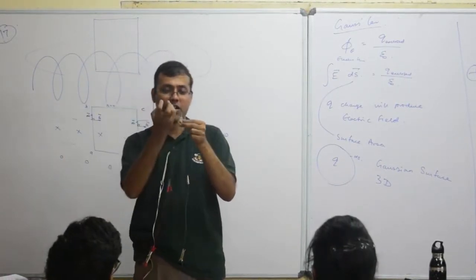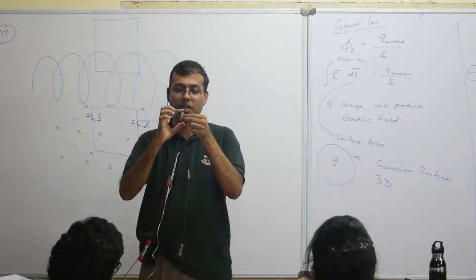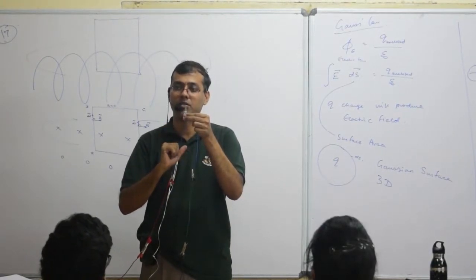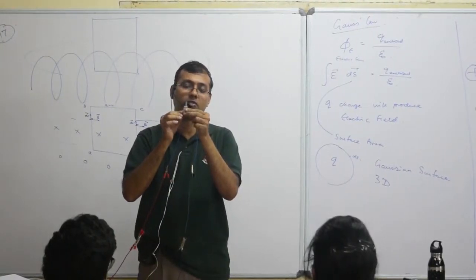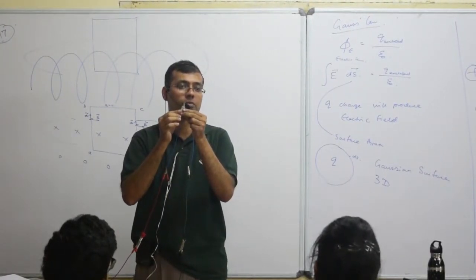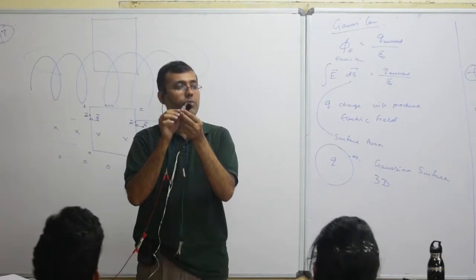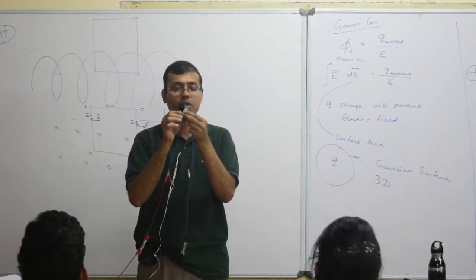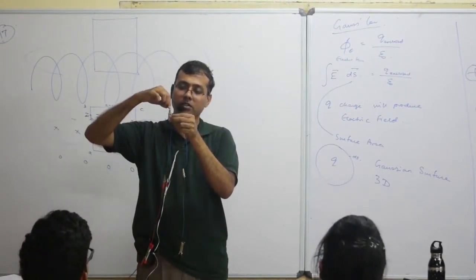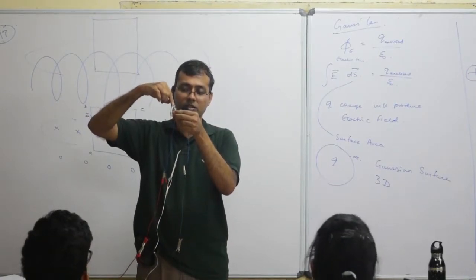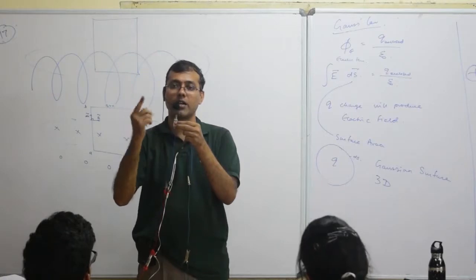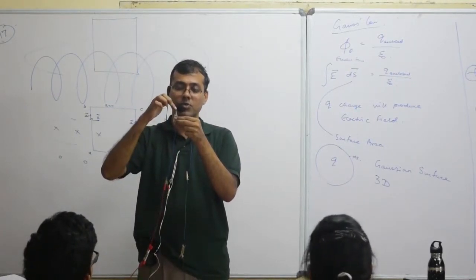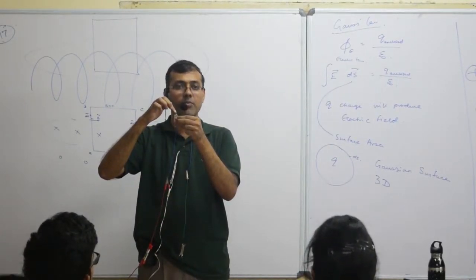When I switch it on, it should just go in, and when I switch it off, it should come out. So it will be connected to some kind of a valve. These kinds of valves are called solenoid valves, because they work based on the solenoid principle. Inside you have a solenoid, and there is an iron core inside this. You can see this is the iron core. When you flow the current, it becomes magnetized, which means it will be pulling inside.